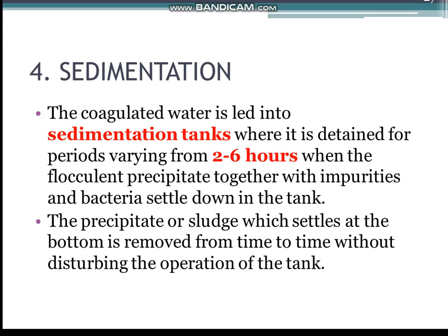Fourth, sedimentation. The coagulated water is now led into the sedimentation tanks, where it is retained for periods varying from 2 to 6 hours, when the flocculent precipitate together with impurities and bacteria settle down in the tank.